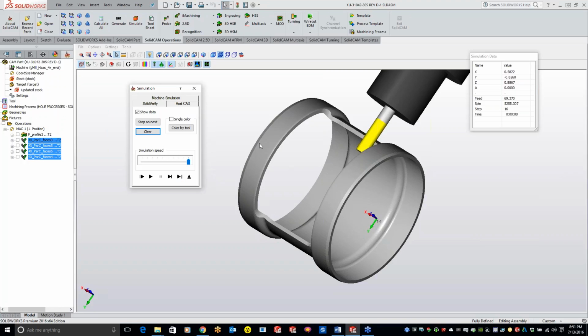As you're dropping straight down on the part, it won't show that slug there for you anymore. And Kevin, the cool part about that particular feature is, you wouldn't really be able to see the entire toolpath if that slug wasn't removed from the verification.